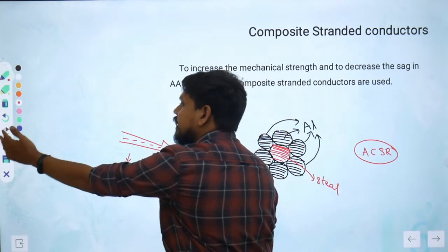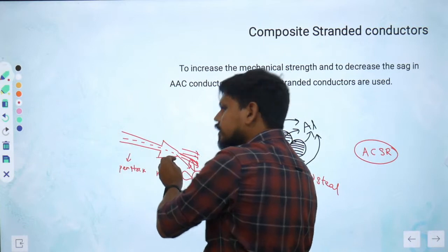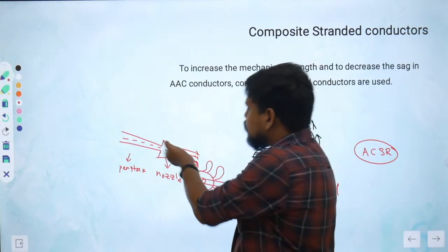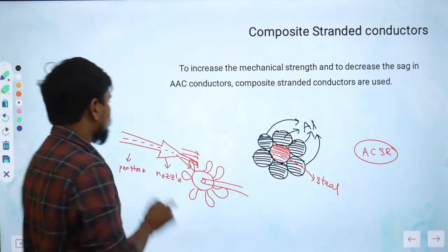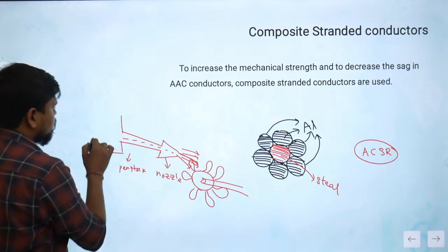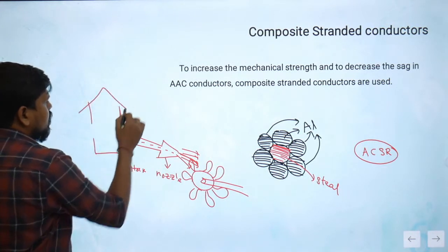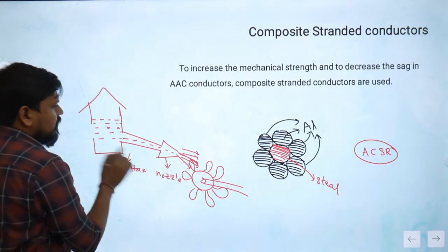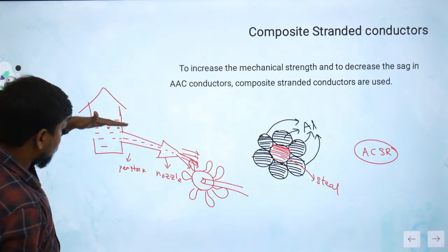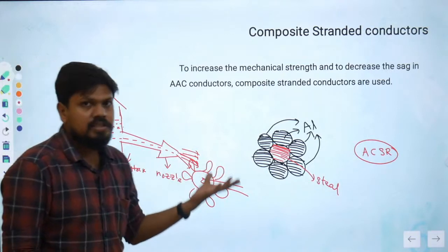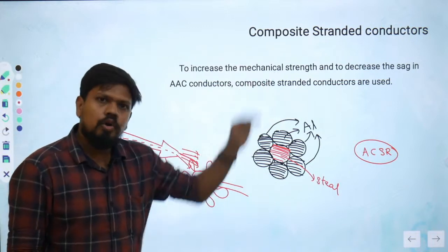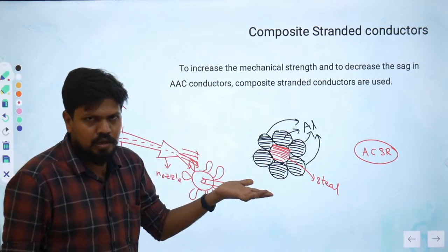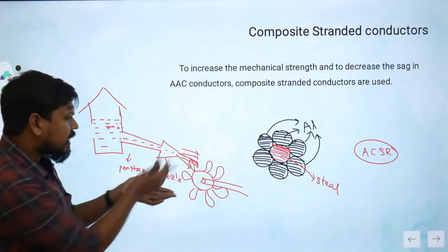From that distance, if water comes here, it will take a certain time, but whenever the load is changing, we have to change the water supply here immediately. So what you will give is some surge tank here. Generally the surge tank will have some external water. Whenever more water is required, this water will decrease. Whenever the load decreases, for example previously 200 megawatt, now it is only 100 megawatt, that means more water should not go; water has to go back.